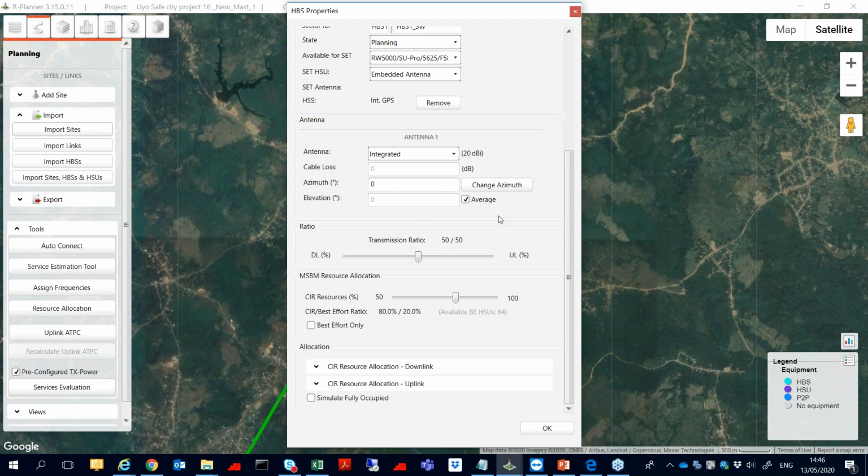At the end, when you change the clock on the uplink and downlink, you're changing the duty cycle. The duty cycle changes the uplink downlink throughput accordingly. So we can play with the ratio. I take it to the left, I have more uplink. I take it to the right, I have more downlink. I take it to the middle, we have 50% uplink downlink.